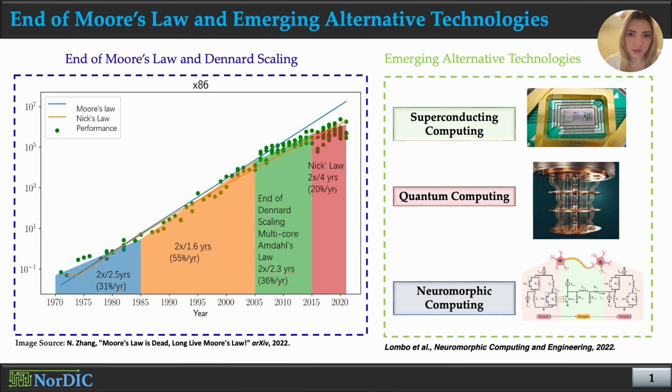Moore's law and linear scaling have primarily driven traditional semiconductor technologies. According to Moore's law, 2 times as many transistors could fit onto a chip every 2 years. Meanwhile, the linear scaling principle states that power density stays constant as transistors get smaller. Guided by these principles, engineers have been able to fit more transistors into a chip while keeping the same power density. However, because transistors cannot be indefinitely reduced, this trend has a physical limitation.